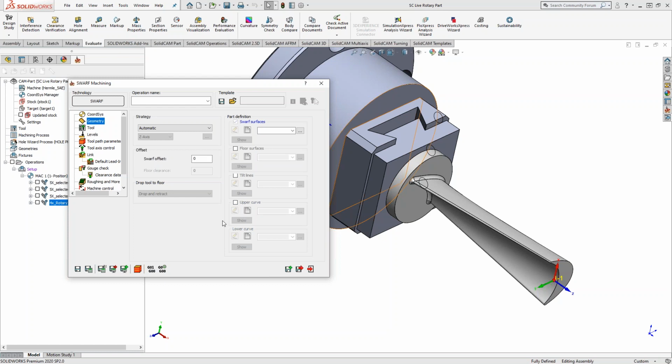This tool path works really good if you guys are doing 5-axis trimming. So if you had a flat part and you were trimming off some, maybe a plastic injection mold, or just cutting the outside of a part, and you had some swarf edges on there, that's where this tool path really comes to shine for you guys.